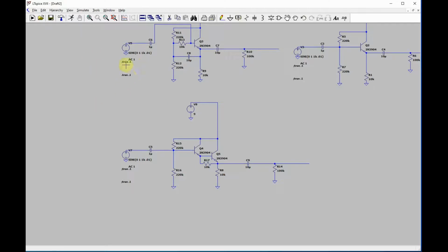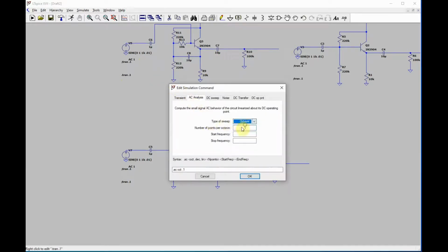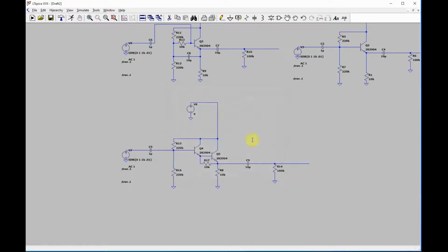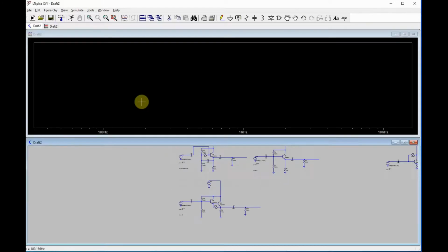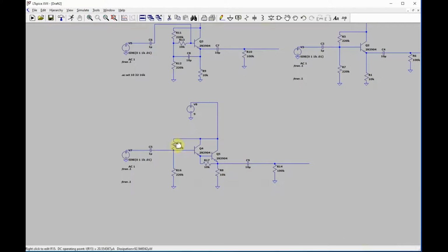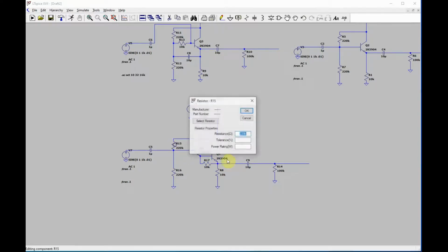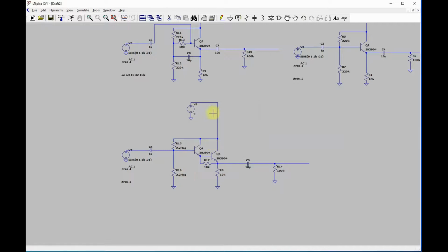Let's go ahead and try this. I'm going to try checking the... Let's see here. So I'm setting up this Bode plot. We're going to see what the input impedance of... hold on. Before I do that, I forgot to change one thing. Since this has such a huge input impedance because it's just this massive transistor, you can just go up on this to like 2.2 megs. That's kind of the point. I failed to mention that. I'm kind of talking as I go.